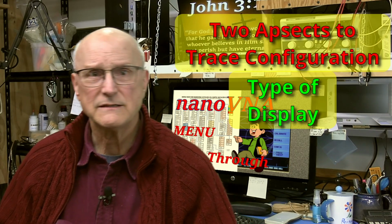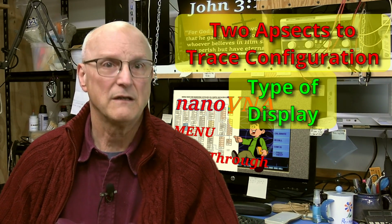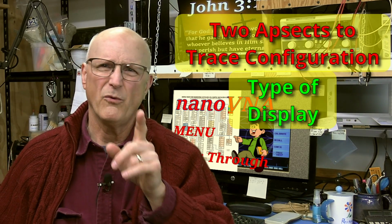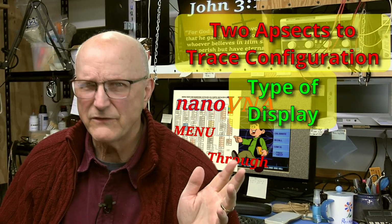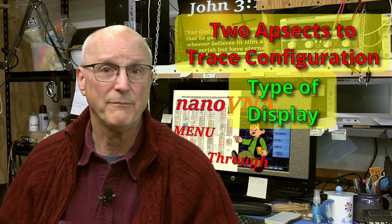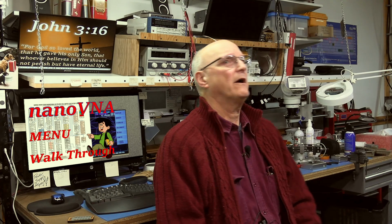The second is the type of display you want to see. This determines a lot about the actual measurement you're making, but it is also about what you're trying to do, too. There are different ways of displaying the same data depending on the thing you're trying to accomplish. So let's look at channel selection first. We are currently at the display menu. On this menu, you will find the channel option. Tap on this menu entry.